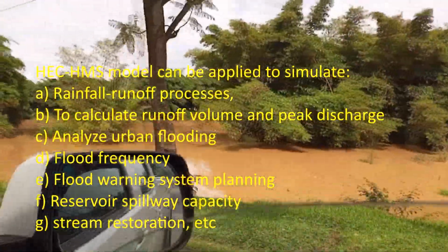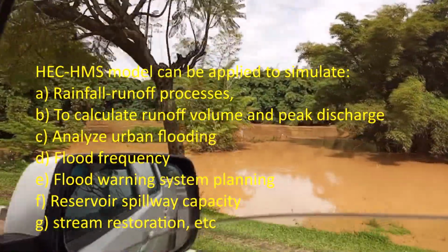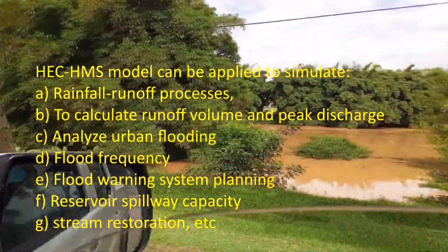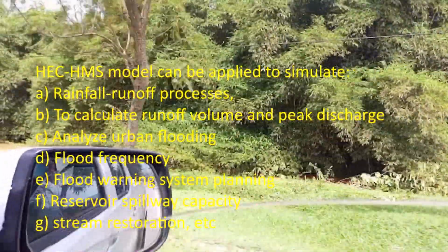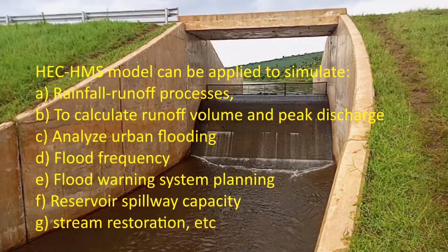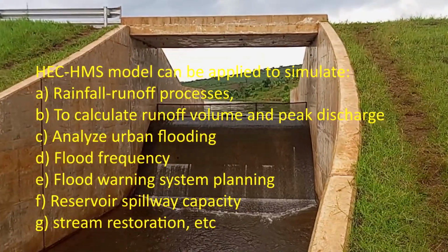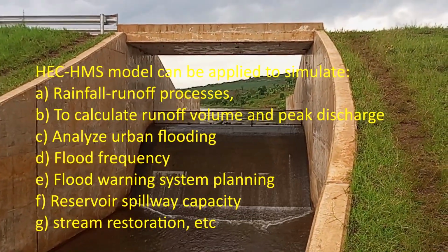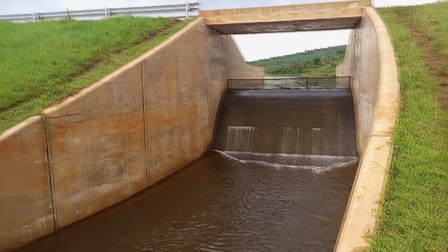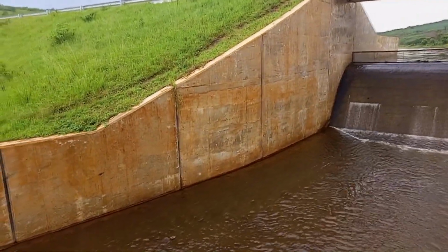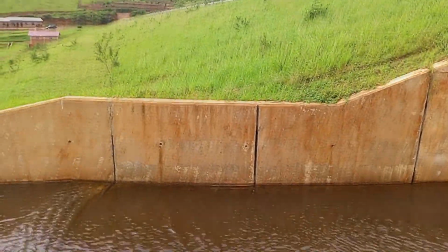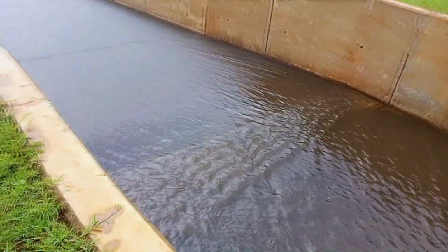HEC-HMS can be used to analyze urban flooding. It can be used to analyze flood frequency. It can be used to do flood warning system planning. It can also be used to calculate the reservoir spillway capacity. The HEC-HMS can also be used to do stream restoration, among others.